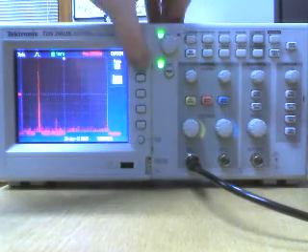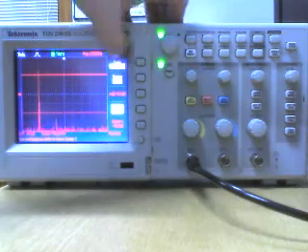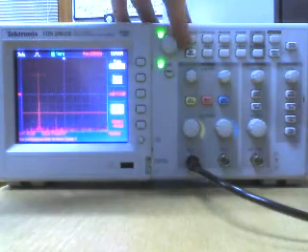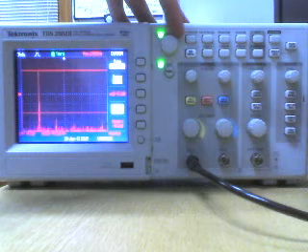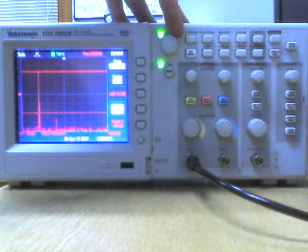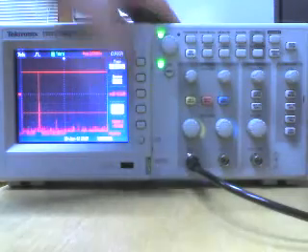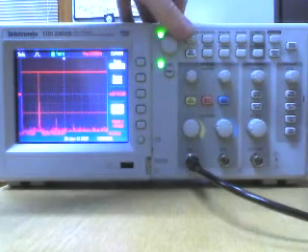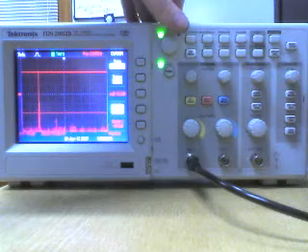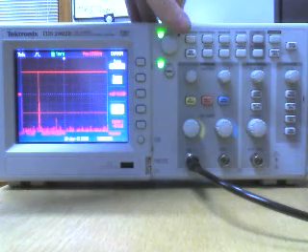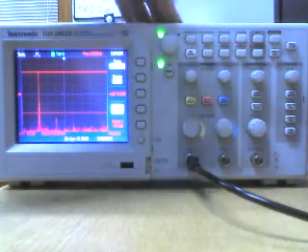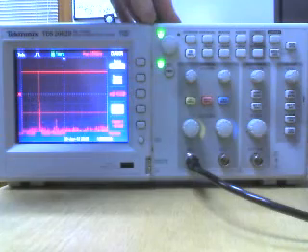Not only can we measure frequency, you can also measure magnitude, so you can change your cursor to actually measure the magnitude. You can place the cursor around the top of the peak, and there we go, 3.39 dBs of magnitude. That is simply using the FFT.